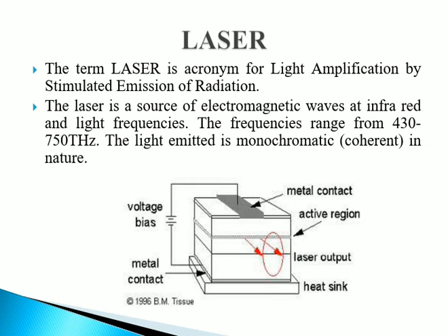The laser diode will be forward biased by an external voltage source. Whenever the electrons move through this junction, electron-hole recombination takes place. Because of this combination, a photon is released. This released photon will strike an atom, and this releases an electron, which in turn creates a hole. These released electrons will again combine with holes. It means that whenever you increase your forward current, a large number of charge carriers will enter the depletion region. Because of that they will excite the atoms.